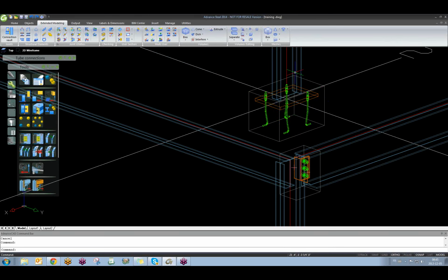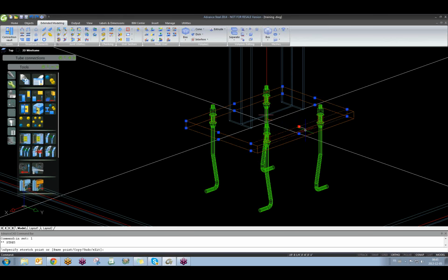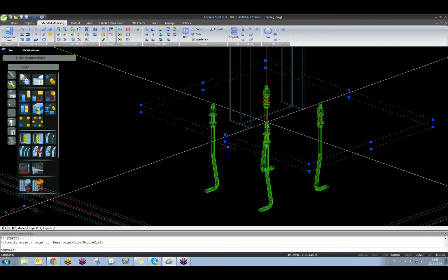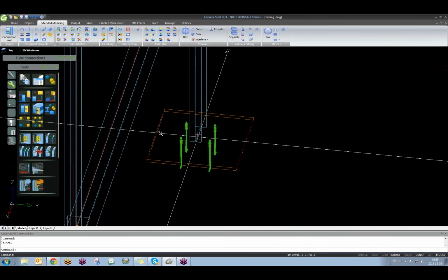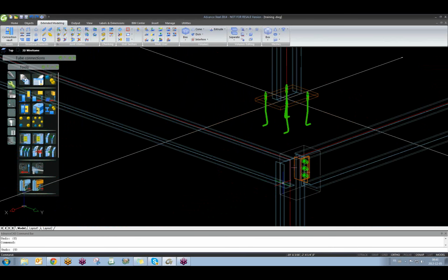Delete one of the components, because when you delete the intelligent box, the only thing that's changed is you can modify it manually instead of going through the intelligent box through advanced joint property and modify it. So what I suggest is just to leave the intelligent box and just select one of the components and delete it.